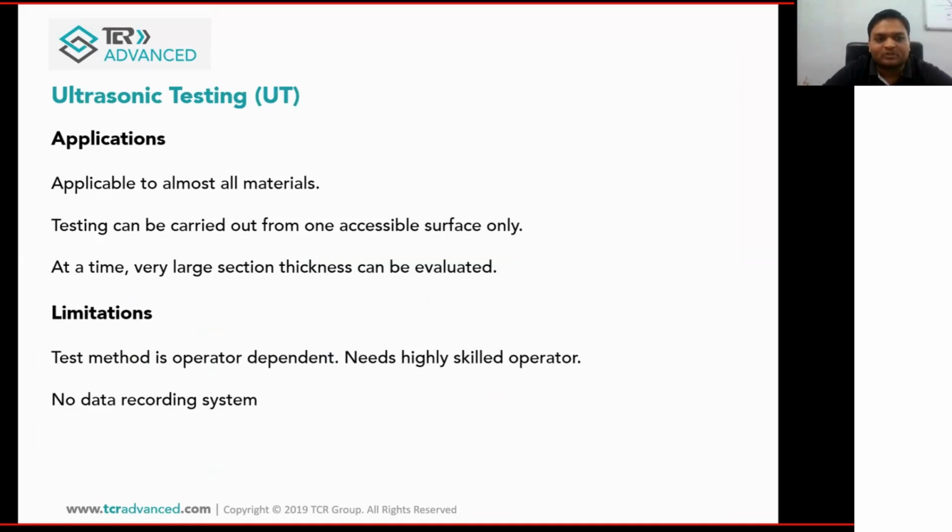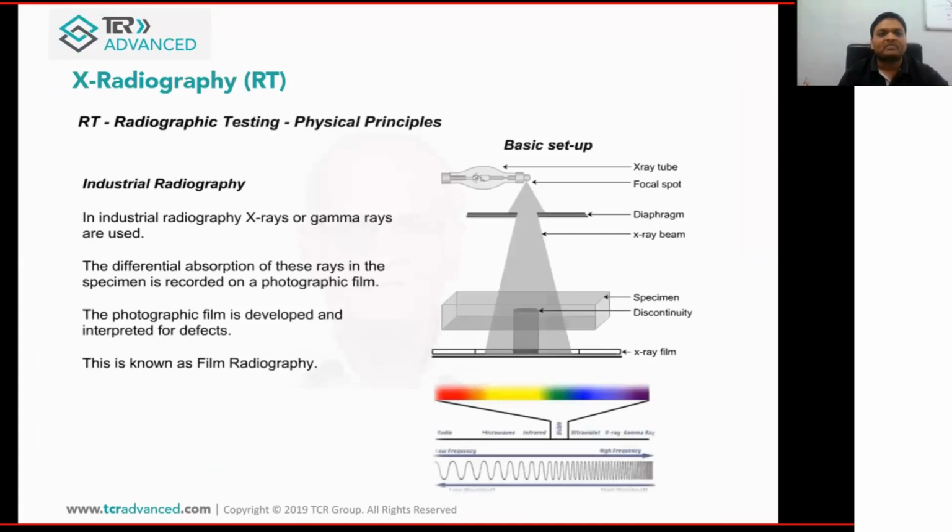Limitations are there. The test method is operator dependent, and we need a highly skilled operator because there is no recording system available in the conventional UT technique. Nowadays, PAUT is available, which is a recordable system. This is also a very popular method.